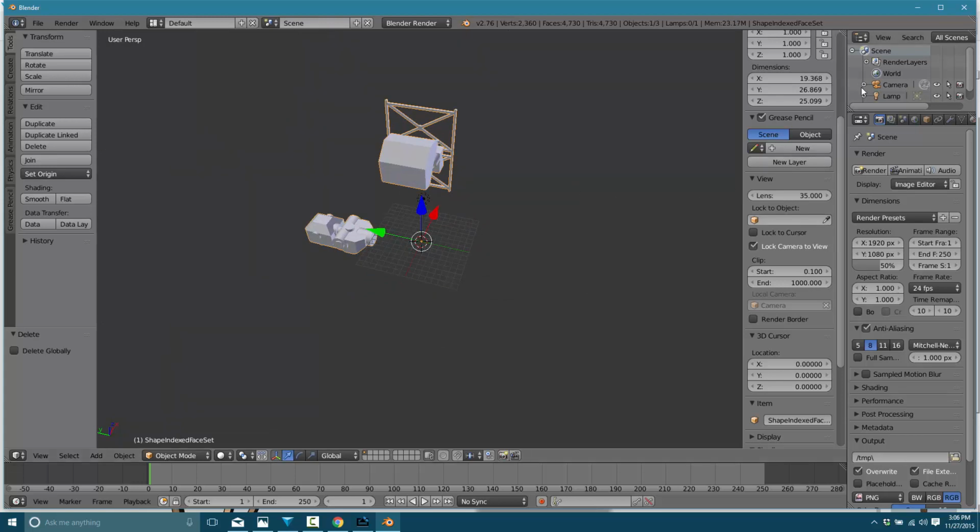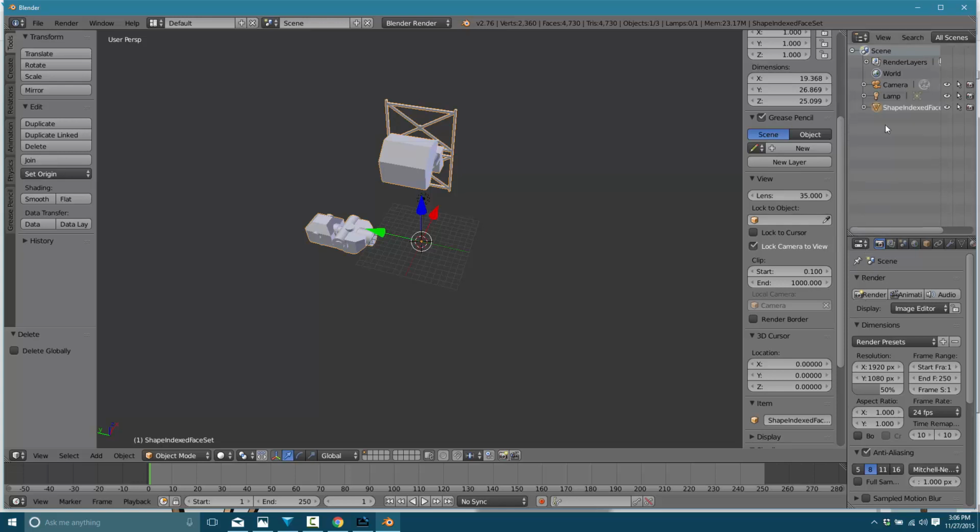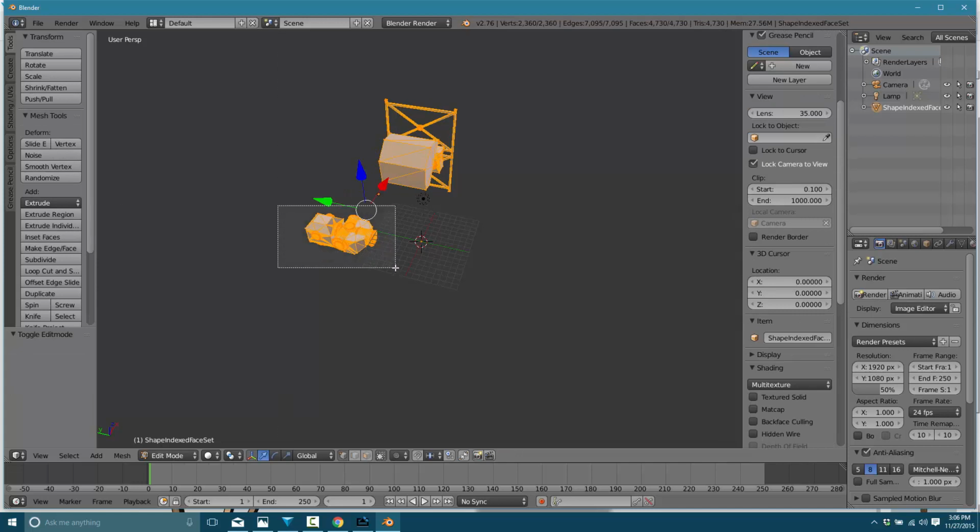And the other catch is going to be, this came in as one single object. So you're going to probably want to model each thing in its own file. It doesn't come in as a hierarchy once exported, at least using the V3D format. Maybe one of the other formats preserves each thing as an individual object, but everything I've exported or imported so far comes in as a single entity. The other thing you'll find, and for example here, this little yellow dot represents the pivot point, or the origin point. You're going to probably want to move it into the center of the object.